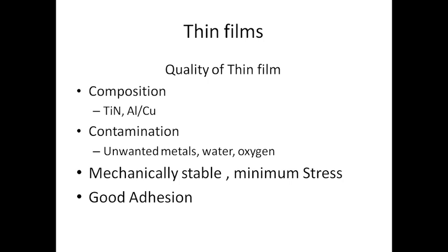depositions. And lastly, it has to have very good adhesion to the bottom surface. It can be a substrate, or it can be some other material which has been already deposited before this thin film. So the thin film should have better adhesion to the beneath material, whatever has been deposited.